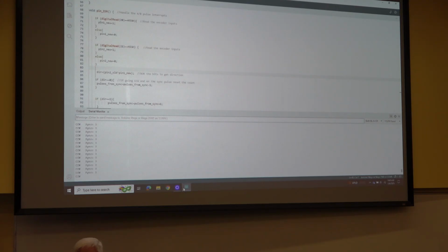Okay, so that little homemade encoder that I had on the table, that is exactly the same as this industrial version. This is 100 pulses per rev, and this one didn't have the little bug that I ran into with the sync pulse on the other one. So if I reset the encoder, I get my junk value, 2,999.